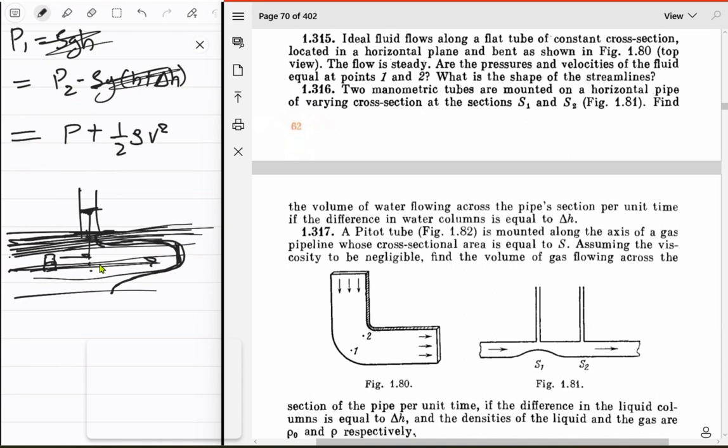Of course, as you move like this, first of all, your velocity in this direction is 0. Only the viscous forces act, because you have a gradient like this in the velocity, right? So your velocity in the x direction is changing as you move along y. You will have to take that into account. Okay, got it. And that will change the speed, right? Yes. And what about the pressures though?